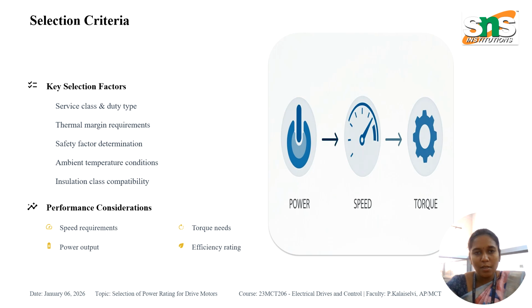Before finalizing the motor rating, we have to verify the service class and duty type, thermal margin, safety factor, ambient temperature, insulation compatibility, speed versus torque requirement, and efficiency level. Only after checking all these should the motor be selected.